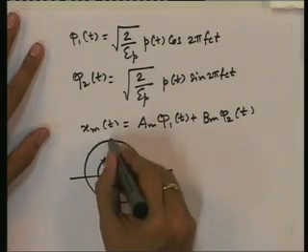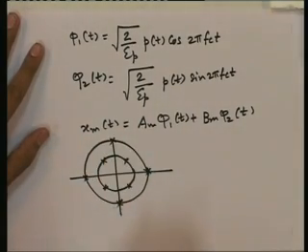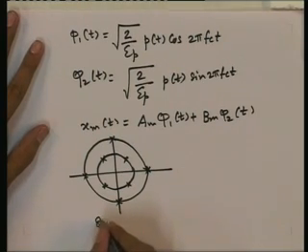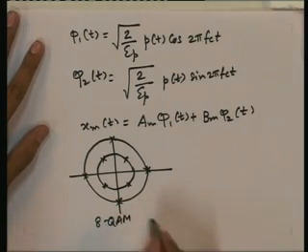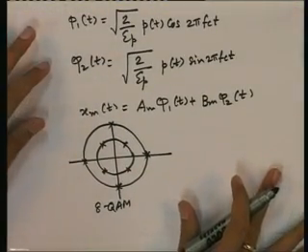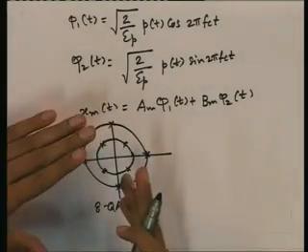Then you take this extra point on a bigger circle. So this is 8 PSK, 8 QAM. So we can have different 8 QAM modulations, different 8 QAM signal sets. We can choose the points this way, we can choose the points in another way, we can choose in many different ways. So let us say we want 16 points.